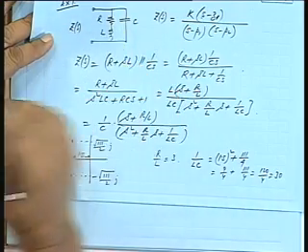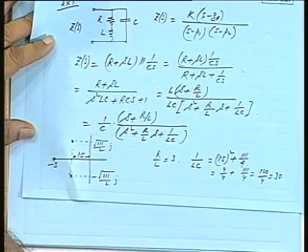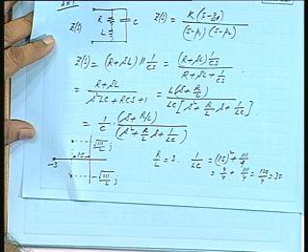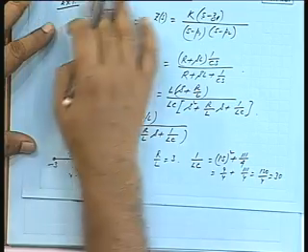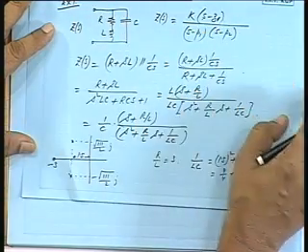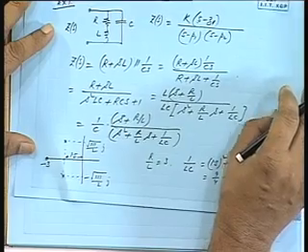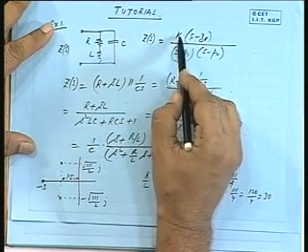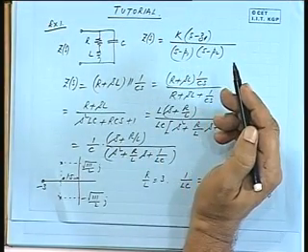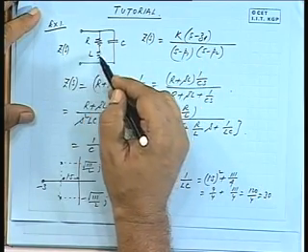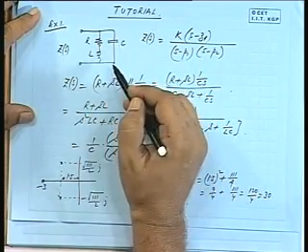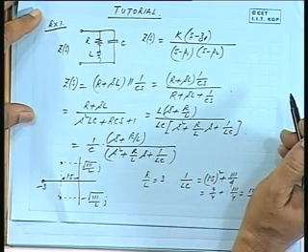There is some redundancy. Can you find that? There is no uniqueness in the impedance function so far as the poles and zeros are concerned, because this K is not reflected in the pole zero distribution. So if I double the resistance, double the inductance and halve the capacitance, then also I will get the same pole zero distribution.